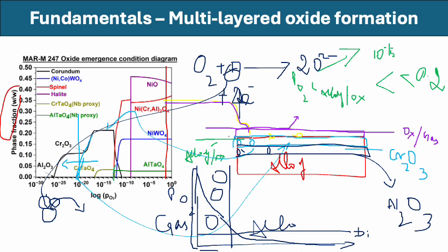So if we can design some pre-treatment for our alloys based on promoting certain kinds of oxides to form over others, we can preferentially tune what kind of oxide layer we form if we understand the fundamental processes that are going on. So this will be practically relevant when you develop materials and design alloys for practical applications in the industry.